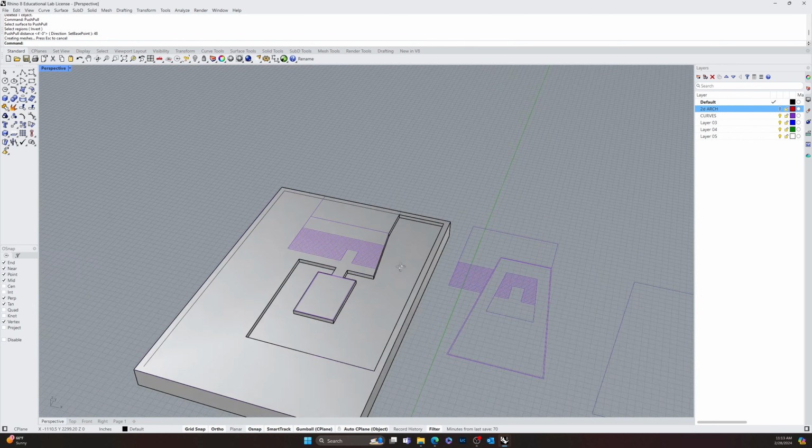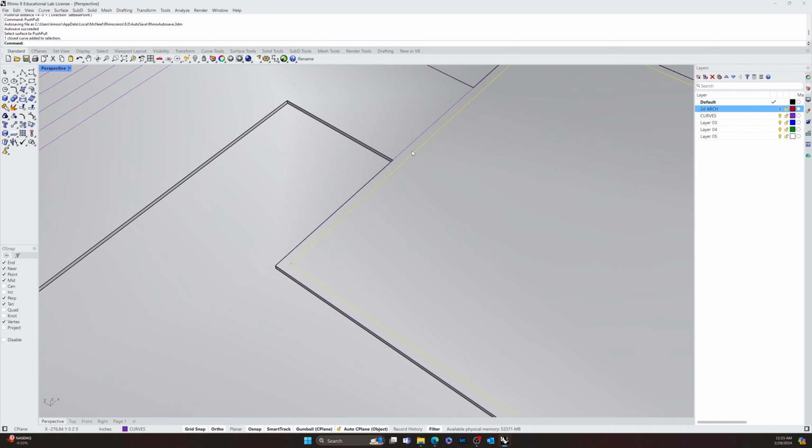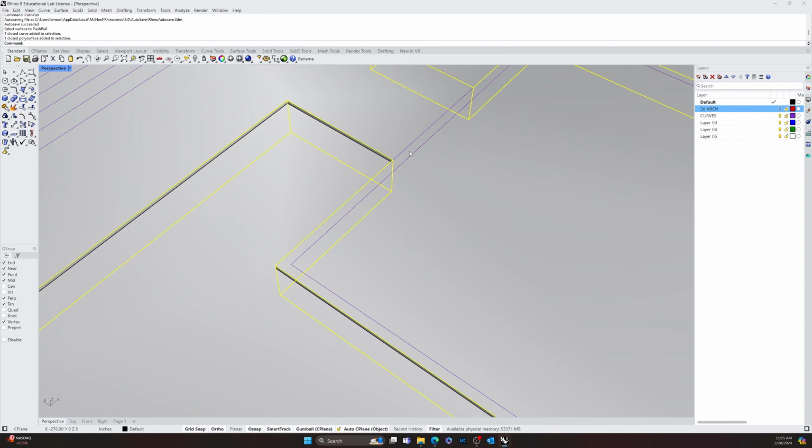All right, let's do the walls here. So push pull this, enter. And how high is our ceiling going to be? I think it needs to be a nice division of, we've got, well, let me see here. Let's do 15 feet. So push pull right here. Nope. There we go. Enter 15 foot. Enter. Okay. So that is going to be the height of that room.